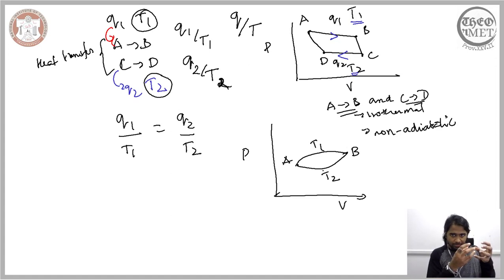So the system starts at A and there is heat that is fed in, and this system is at temperature T1 and there is a specific amount of heat that is fed in, and there is a change in the state of the system from A to B. Now the system is at temperature T2 and there is a removal of a specific amount of heat, and this brings about a change, and both these changes are equal, and therefore we end up where we started. So essentially what we have arrived at is a cyclic process because we have ended up where we started. And secondly, whatever changes we have made by feeding in Q1 at T1 have been reversed when we removed Q2 at T2. So what essentially we have is both a cyclic and a reversible process.